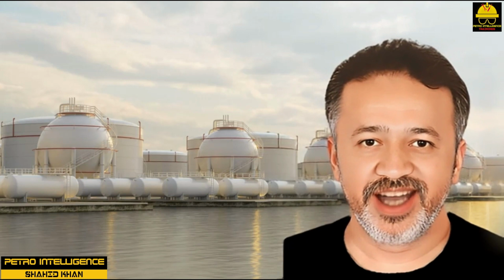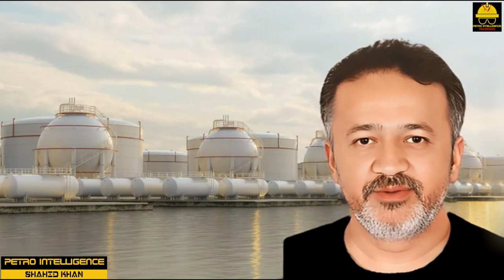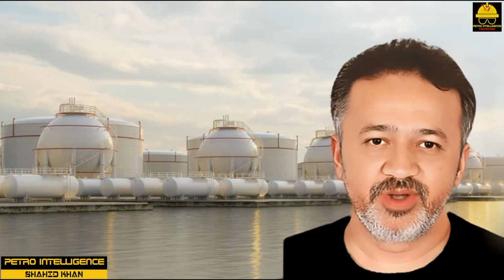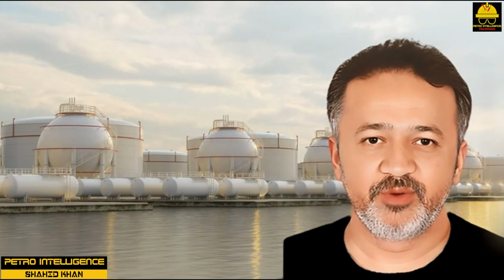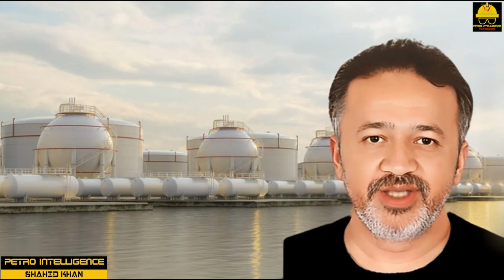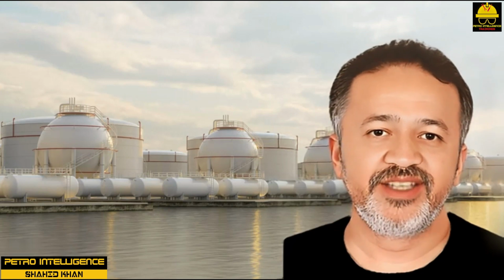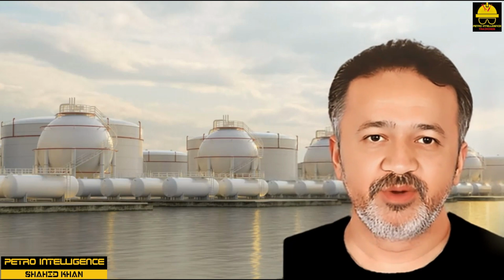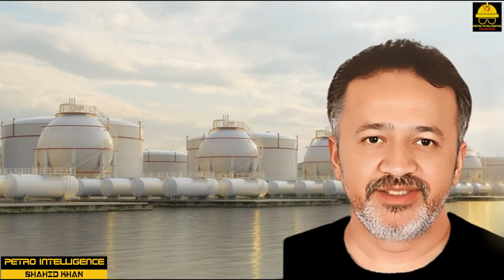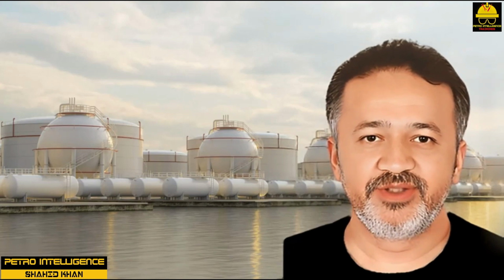Inspection frequency and extent. The frequency and extent of inspection depend on factors such as pressure, temperature, corrosive action of the materials handled, materials of construction, corrosion allowance, and past experience with the equipment involved. Equipment in high-pressure, high-temperature service subject to corrosion is, of course, inspected frequently. On the other hand, some equipment may require complete inspection only once in 5 years.